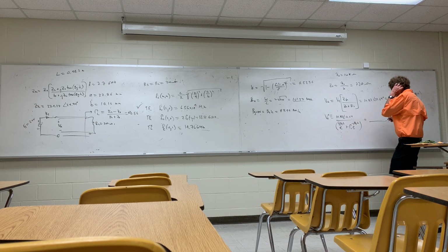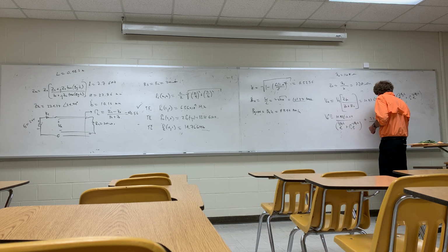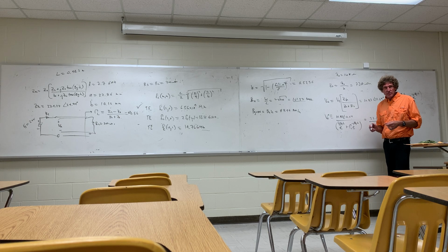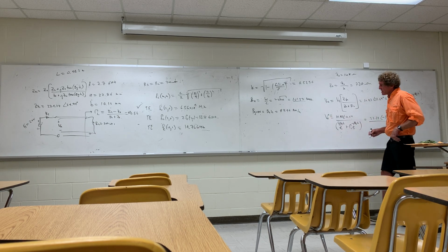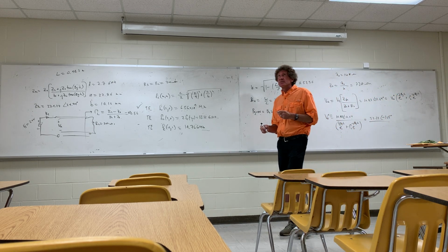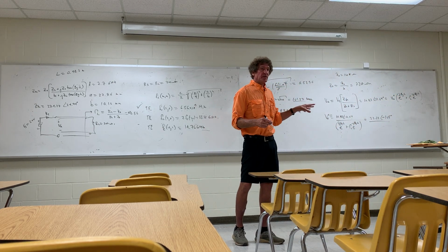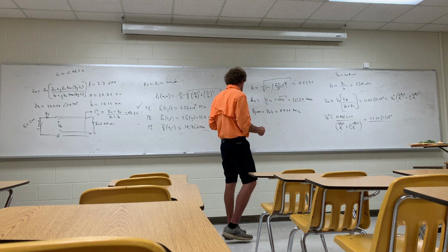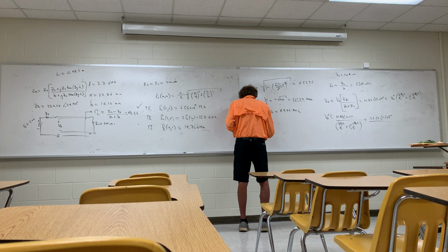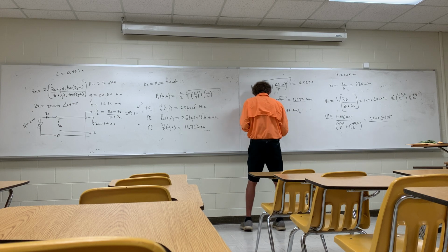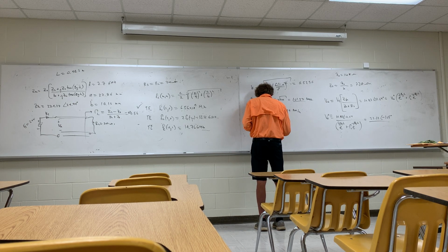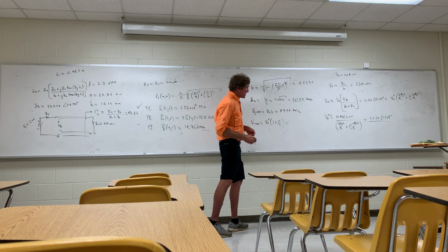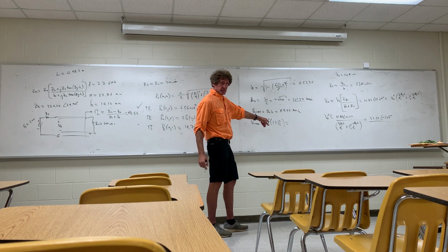22.22, an angle of negative 165 roughly. Is that about what you got? So if that's V0 plus, then after that, they ask for the voltage at the load. You need this to get it. The voltage at the load will simply be equal to V0 plus times 1 plus gamma L. And so you're simply going to take that times this to get it.